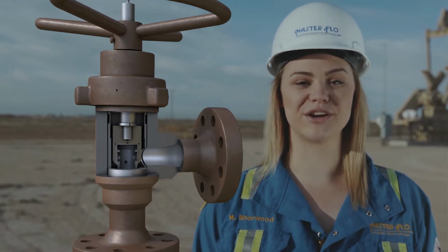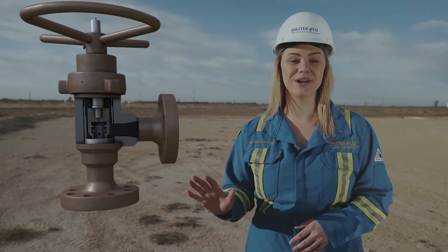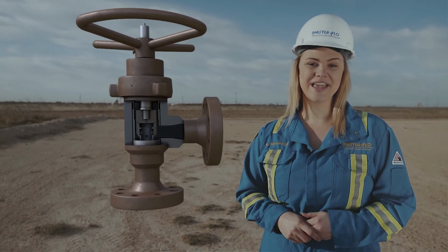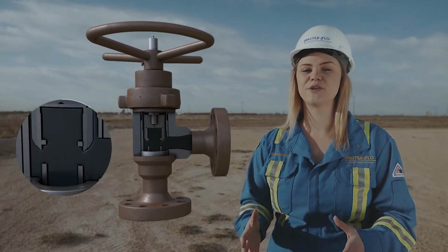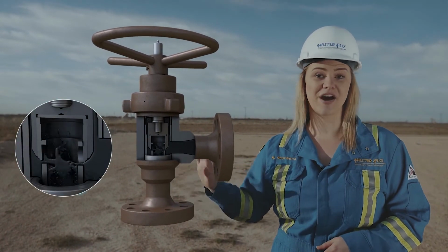This valve is best for high pressure drops and high sand concentration applications. Moving the seat to the outside, where the fluid velocity is lower, reduces wear to the throttling surface and improves seat life. Reduction of valve outlet erosion is another important element of the external sleeve. It's achieved by directing the fluid exiting the throttling port into the valve trim and away from the valve outlet.